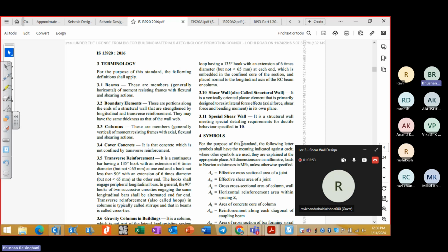But when you are dealing with the concrete element, you have to define it as a shell element, right? So shear is more dominating. For steel plate shear walls, it is made up of plates but dominating in shear forces. So while definition, you have to make sure that what you are defining obeys the requirements.